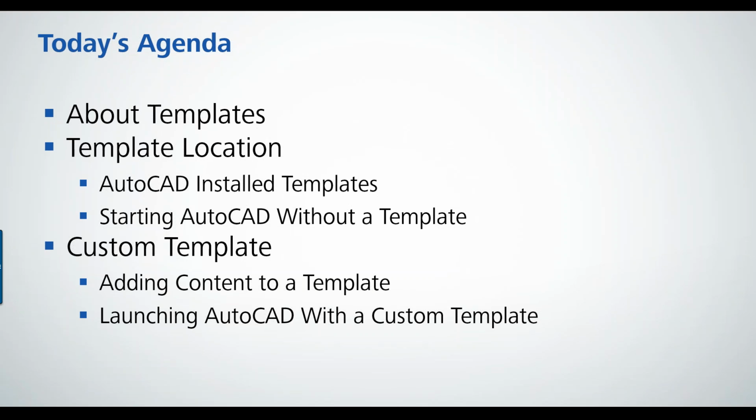The other one is if you ever have a problem with your drawing files, and the same issue occurs with one of the installed templates that you have, you could start AutoCAD without a template to see if the same issue exists in a blank canvas. We're going to create a custom template, and we'll be using things like Design Center and some existing drawings to do this. And we will show you how to launch AutoCAD with your custom template.